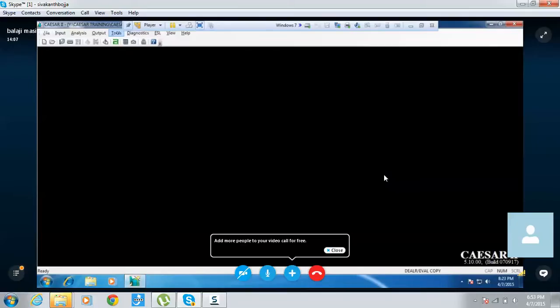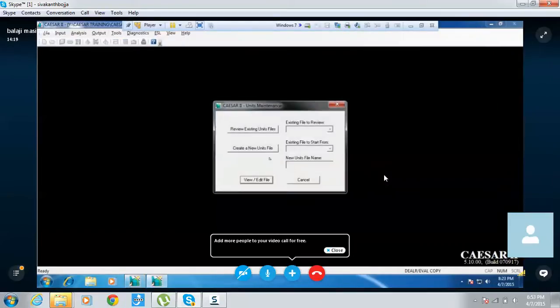You know that? Yeah, Tools, Make Unit Files. Unit file. Yes. In that, create a new unit file. New unit files. Okay, existing. In that, you just note it down. mm.file, and after that you have to enter which unit file you want to make. I mean, any name you can give.